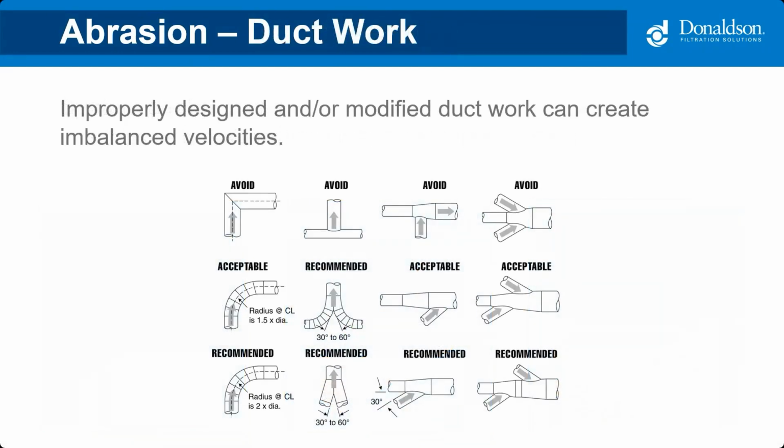And then also ductwork. I'm not going to go through this one by one, but just avoid 90-degree turns, avoid bringing in ductwork at a bad angle. And a lot of this stuff happens when you put a new grinder on and you're just like, just run it over and stick it in that ductwork.